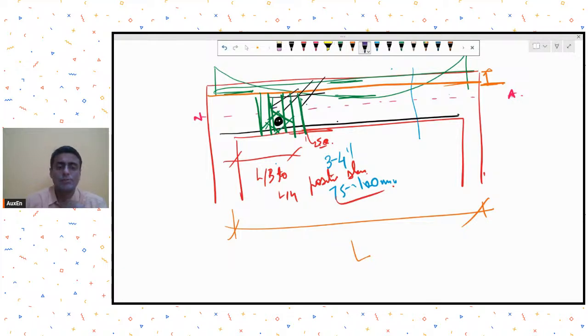In this case also, I can fix up a GI pipe which will act as a stable, strong core around the sleeve, and I can in fact weld my stirrups to this. And if required, some side bars also, and then I can do the casting. So this will behave as a very good stable system. This is what I can do in cases of small sleeves, small openings.